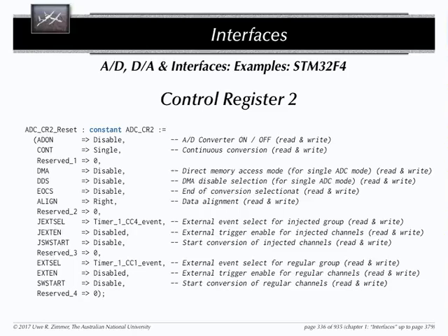Smaller stones, smaller springs. If you make it small enough, these smaller stones turn into, for example, piezo crystals, suspended by touching other crystals, and they get into an oscillation. Depending on the pressure on different surfaces, the frequencies you get out of your piezo crystals will change a little bit. You can then measure acceleration or gyroscopic effects if you carve that thing right.